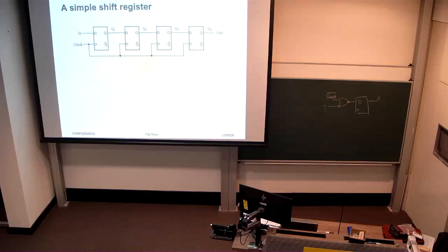This illustrates a shift register, a 1-bit shift register, in which case the input bit in here is loaded into this leftmost flip-flop when we get an active clock edge. And that, of course, appears on the Q1 output after the positive edge comes along. This is a positive edge-triggered flip-flop.